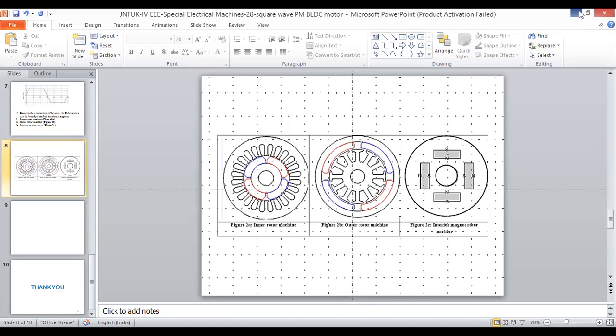In permanent magnet machines, the necessary rotor flux is present due to the rotor permanent magnets. Currents in the stator windings generate the stator MMF. With respect to the interaction of the rotor flux, the stator windings can produce an EMF, which is called the back EMF. The stator flux and the rotor flux, also called the stator MMF and rotor MMF, have zero relative speed.